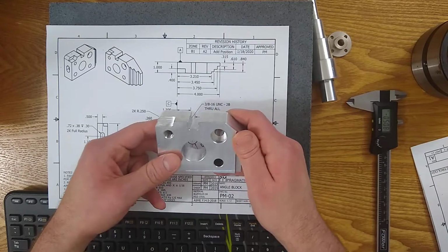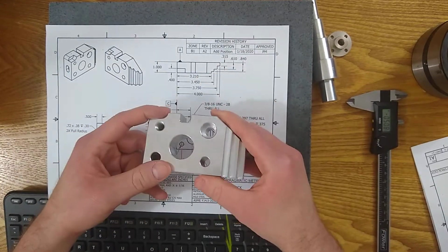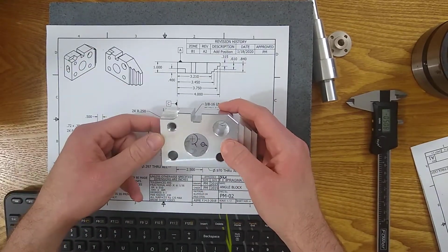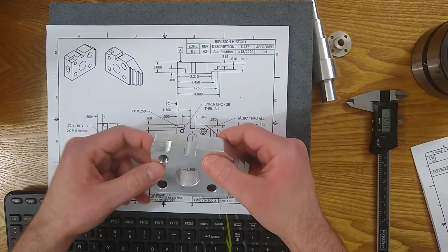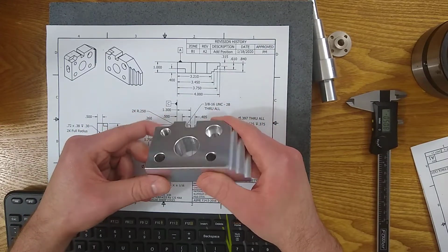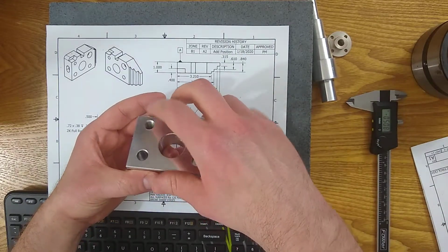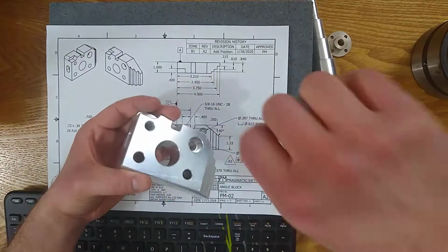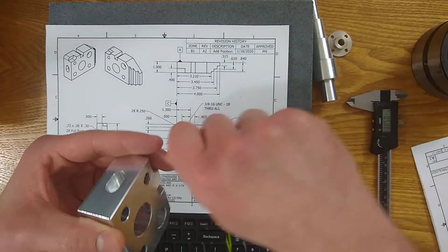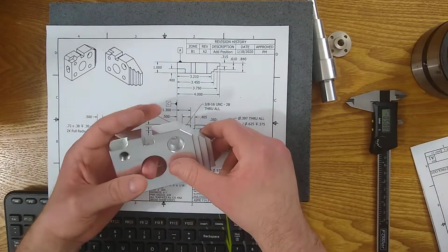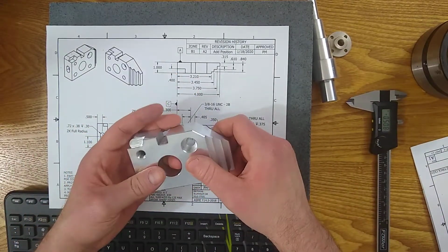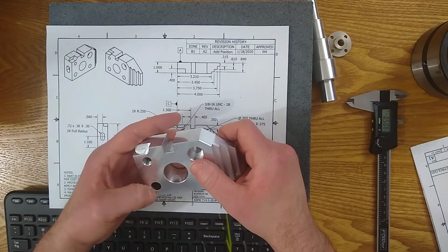So as an inspector, you probably won't ever get that far. Maybe there'll still be a broken tap in there if they bring it to you. But just remember that even though we're not inspecting the minor diameter or the other features, wiggle that gauge, see how loose it is, and you will be verifying the thread.